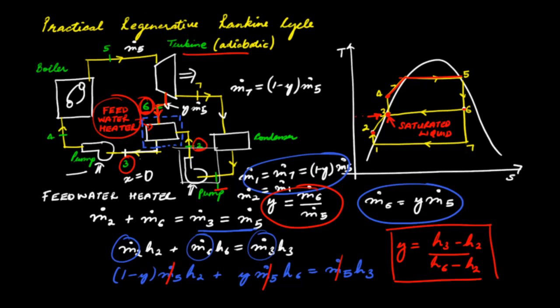And note that on this cycle that is shown on this TS diagram, in this case one should just consider that this cycle just shows the state of the working substance. Because the mass flow rates through different components differ, one should be careful to interpret the area under the various parts in terms of the heat that is added or removed and the work that is done.